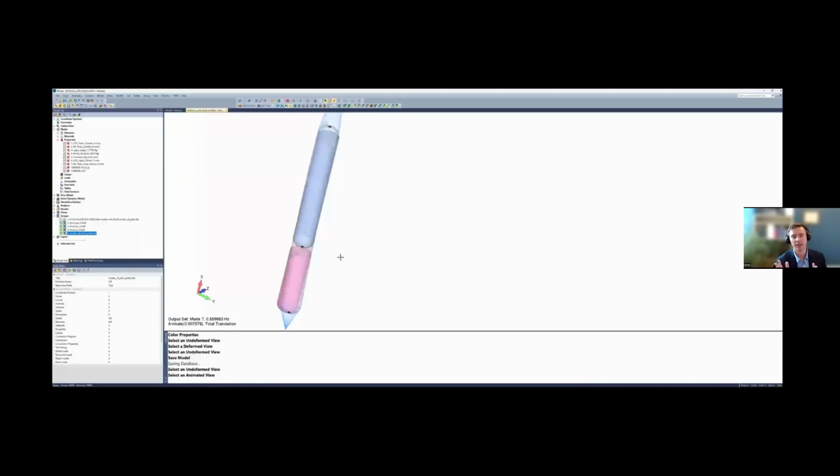It doesn't have any displacement degrees of freedom, so you won't see any mode shape result associated with that. But that's exactly what this underscore plot L dot dat mesh is for. So if we hide the fluid elements, now you can see the slosh motion on these plot L elements.